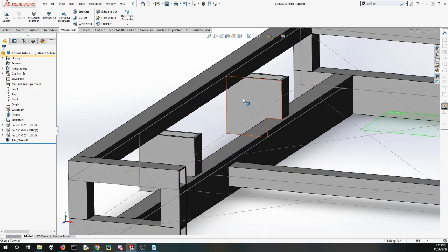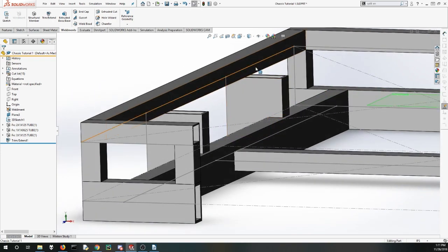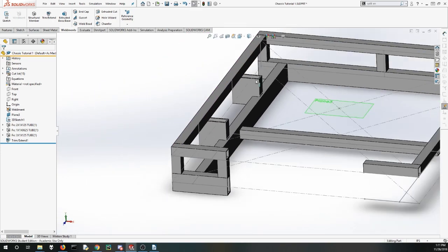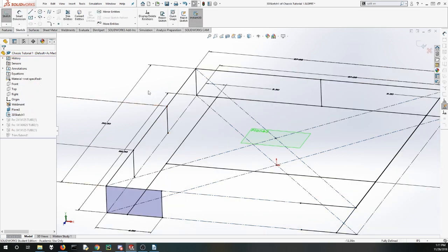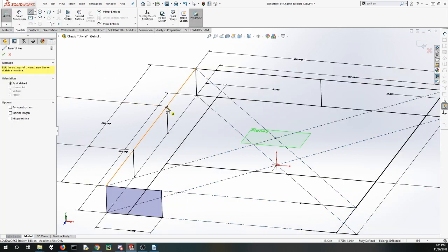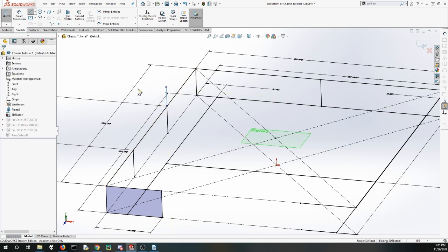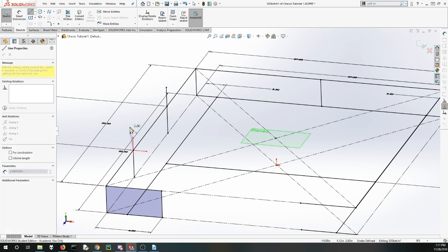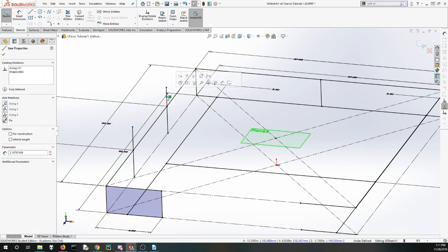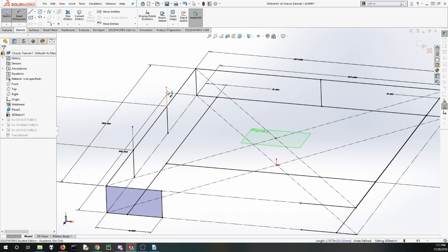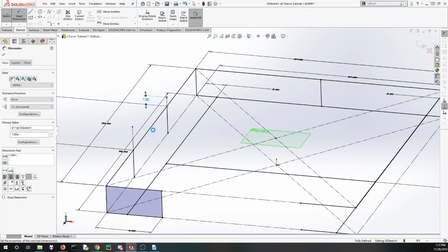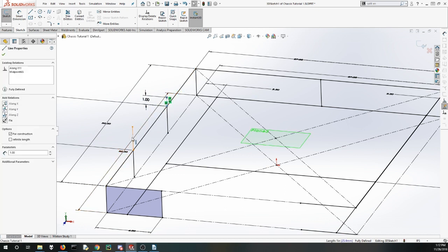And we might want the same thing on the top, but the tube's not long enough to get up there quite yet. So I'm going to fix that right now. I'm going to select Edit Sketch, and a quick way to do this is to just draw a line to another line, make both of these construction, and make them both 1 inch.